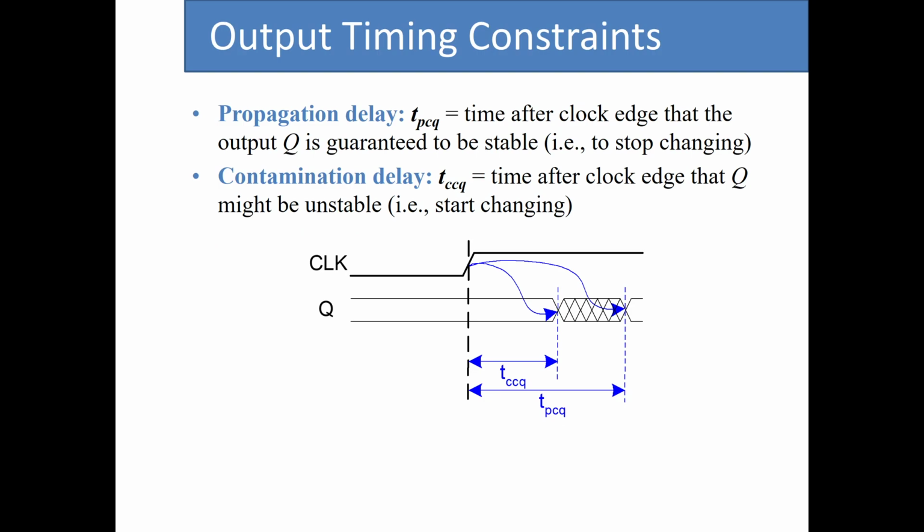So that was for the stability of the input of a flip-flop. What about the delay that we may have for the output of the flip-flop? You remember from before, for the combinational logic circuit, we said that for an ideal circuit, when we change the inputs, the change at the output happens instantaneously. But in real life, depending on all different types of conditions, when we change some input, it may take some time for that change to be reflected at the output.